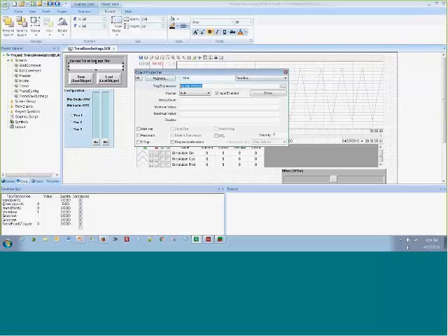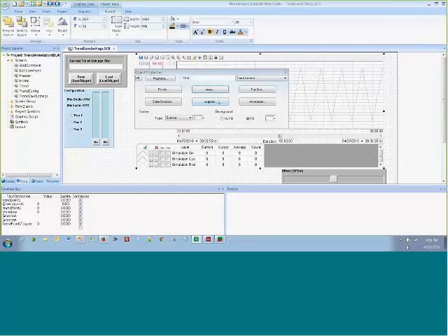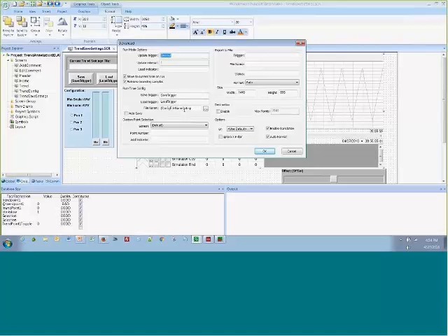Basically here I'm using this interface to change the config file name, and then I'm triggering the saving of that. And if I go here into this trend, click on advanced, what it's doing is changing the config file name, and notice that's inside of curly brackets, and it's saving this in the file extension STMP, and that's the trend configuration. It saves all the different pen colors and line thicknesses and durations and start and stop and all that.